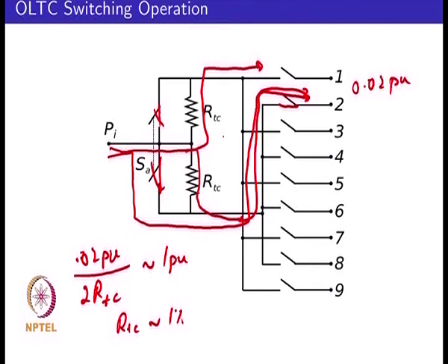You might be operating a transformer maybe in many tens of minutes, maybe an hour. It's not like something that switches very frequently. You are trying to ensure that over the course of the day, when the voltage levels over a longer time frame changes, you want to ensure that your secondary sees the nominal voltage.